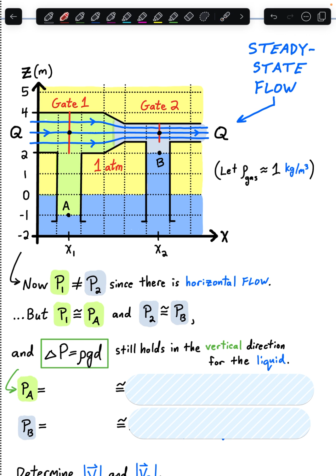So where should we compare the pressure at point A to? Let's pick this location right here, at the gas-water interface, some location there. We can compare that to A because there's no flow of fluid over in this part of the water, no vertical flow anyway, so our hydrostatic equation should apply comparing those two locations.